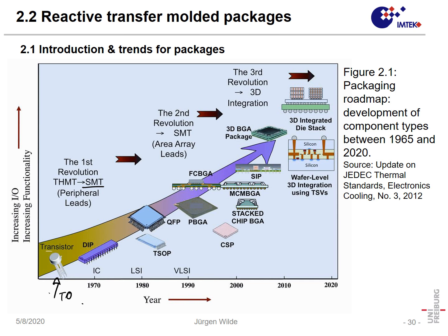And here we first had devices which have the IOs only on two sides, or they have IOs on all four sides. These devices are just put on top of a printed wiring board on the solder pads and are soldered there.